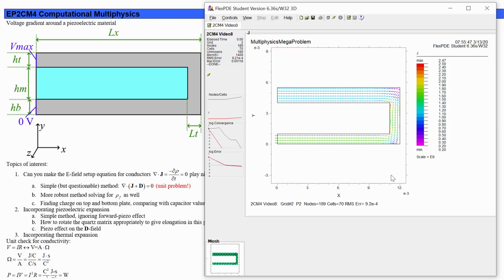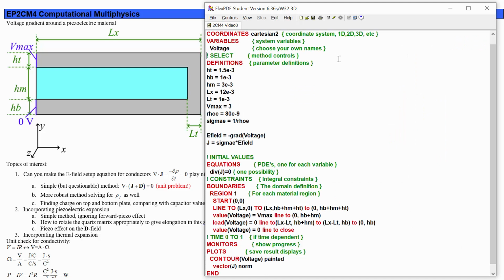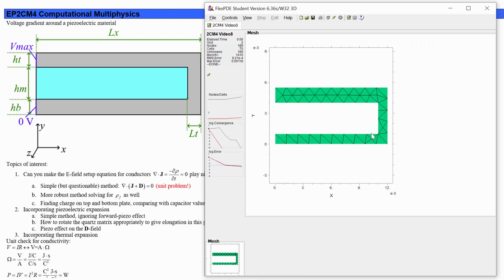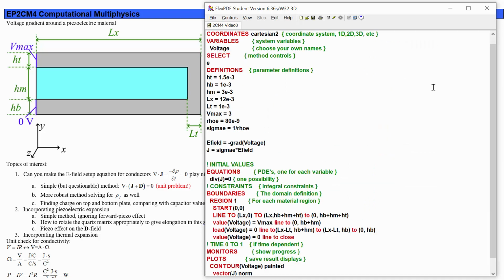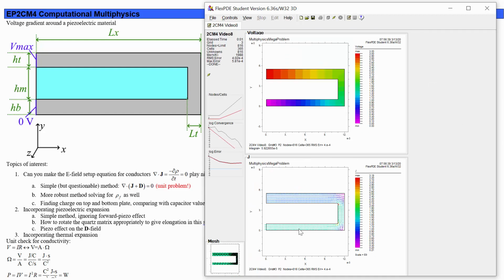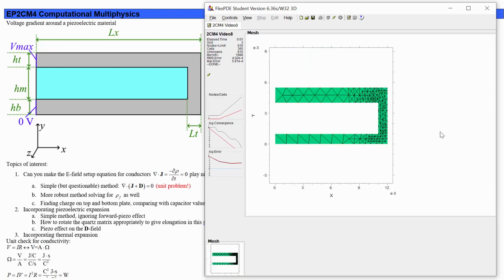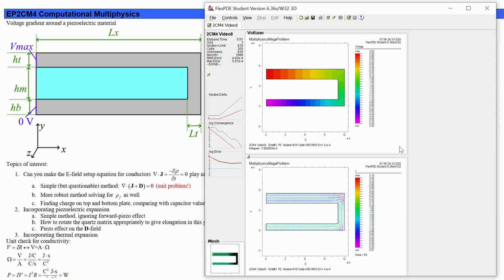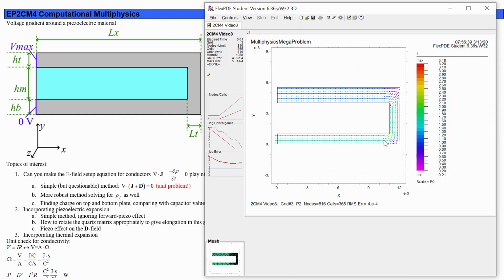Okay, so we can maybe improve things a little bit. The mesh is not looking so dense there. Maybe we can improve things by specifying error limit is 1e-6, so give a relative error that's lower. And yes, indeed, the simulation decided, you know what, we don't really need a lot of density over here. There doesn't seem to be a lot happening. But right around here, ooh, that's kind of interesting. There's some curving going on. We need a lot of extra mesh density built in. So that has smoothed things out here.